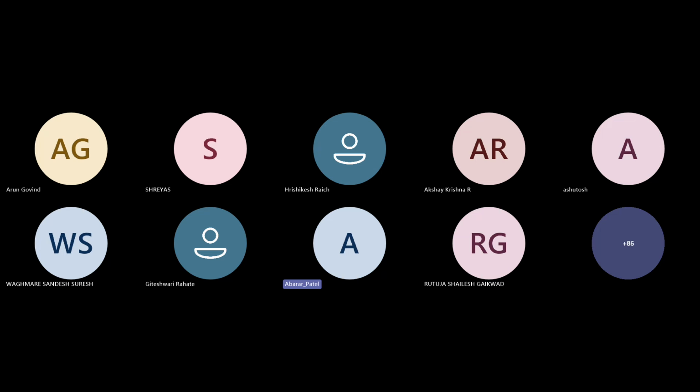How can we get reference for gradability or how can we get the actual value? So gradability reference is generally included based on your design. When you do your traction calculations, you assume certain gradability and then use that in a certain formula to calculate the torque at certain gradients. So you can fill that in as an actual value. You can fill that in software.